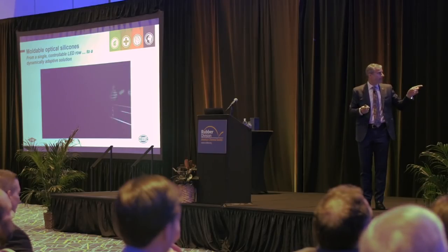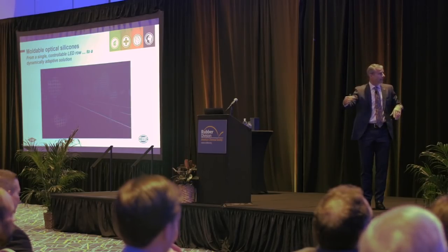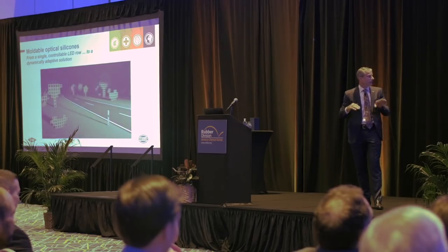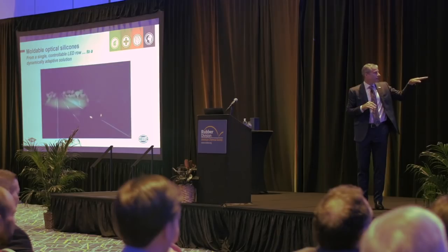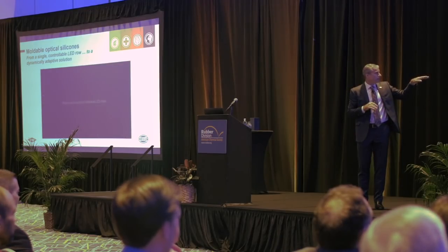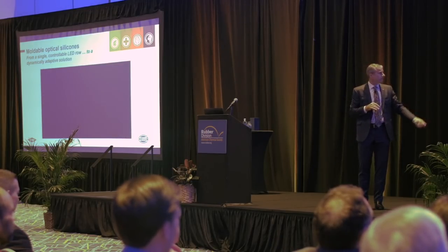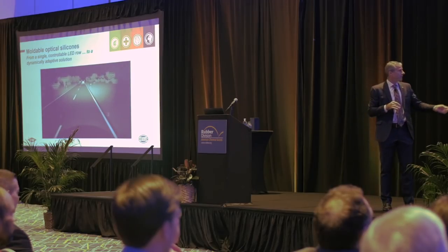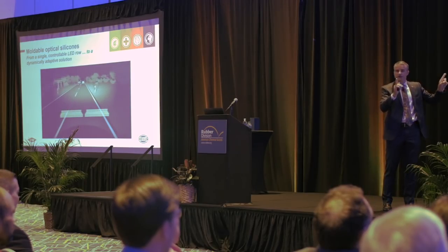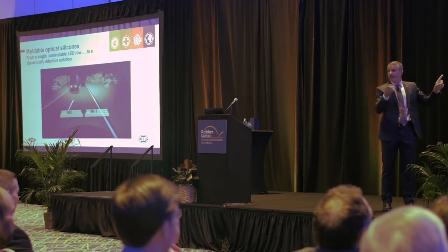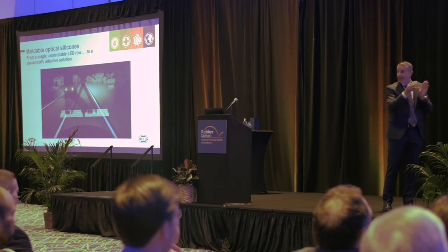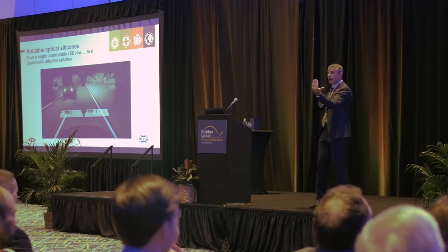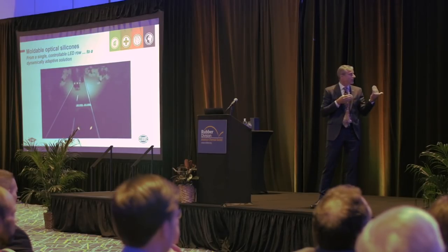You see the car now coming from the right side into the picture, and it goes along. And now it starts sensing there's a car coming towards it. And now it gets close. Now it starts deactivating certain LEDs out of this. And at less than hundredths of a second, it feeds back all the time. So all these angles are now blocked out. And as the car moves towards it, it constantly changes and adjusts it.